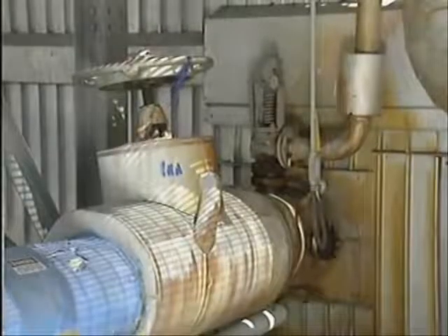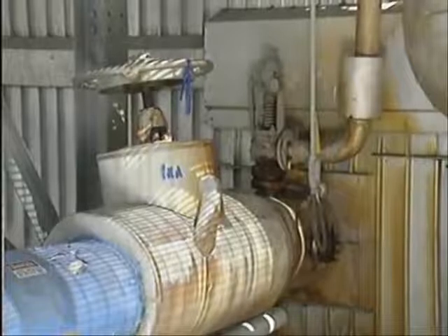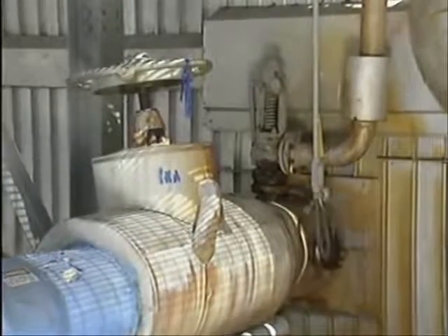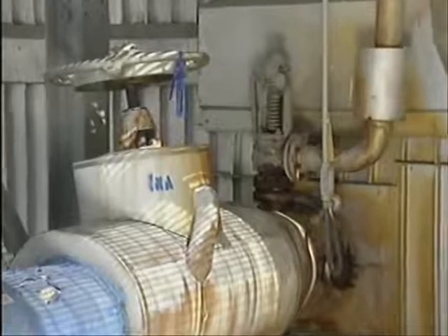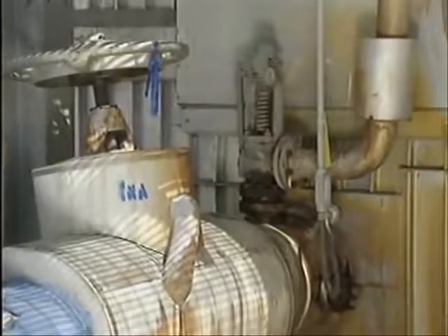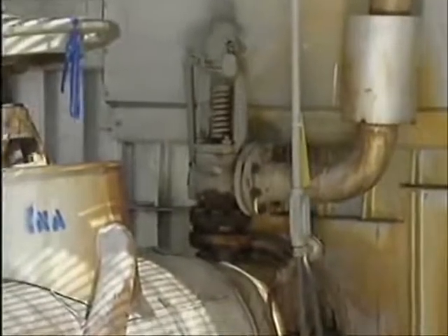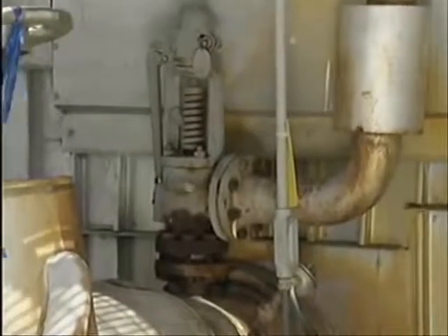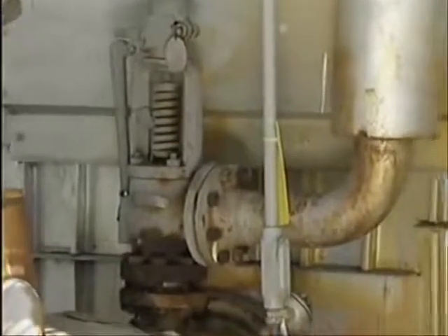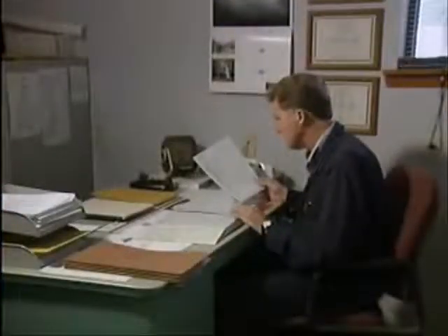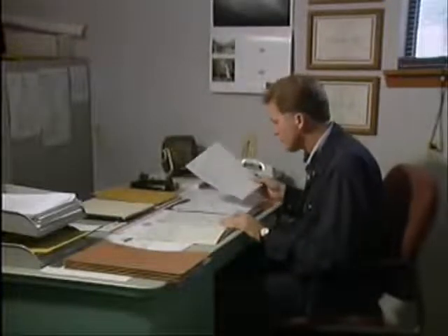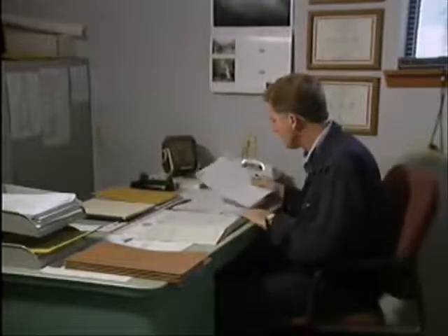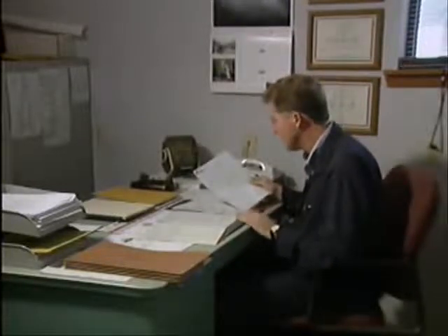External inspections of safety valves are conducted when a problem is suspected, and also when routine preventive maintenance or testing is scheduled. In this part, we'll see a typical external inspection, and we'll look at hand lifting a valve when the external inspection indicates that certain problems may be present. In preparation for an external inspection, check the operating history of the valve. This will give you an idea of specific problems that you should watch out for during the inspection.